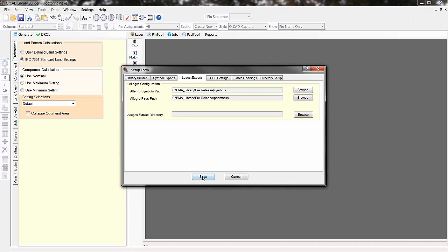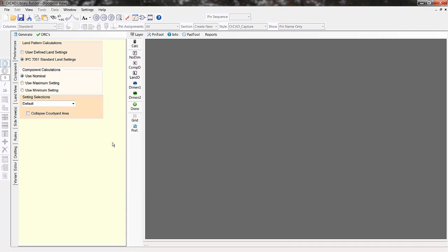Remember that here we are building a part in a local file format, and then to get it into OrCAD Capture and to Allegro requires a file export pull down menu command. So you would export it, and it's going to write the logic symbol or the footprint to those appropriate tools in those two tool formats.